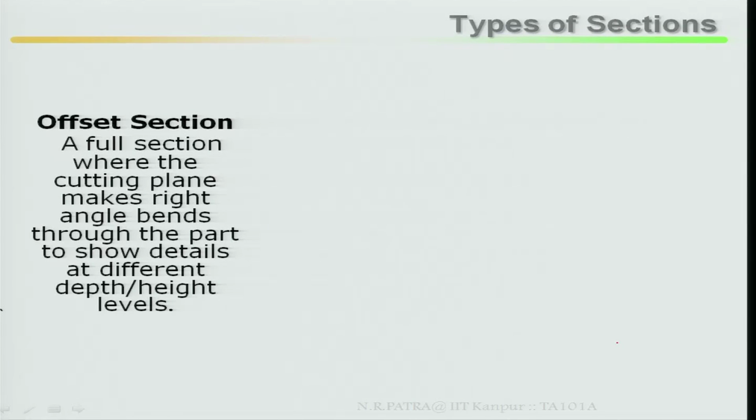Offset section: a full section where the cutting plane makes a right angle bend through the part to show details at different depths or height levels. Remember this one.